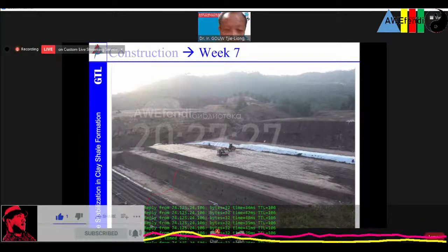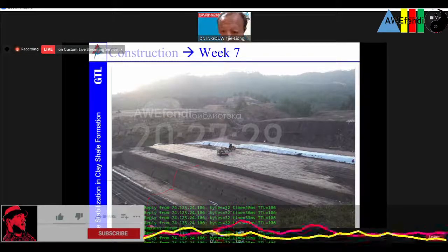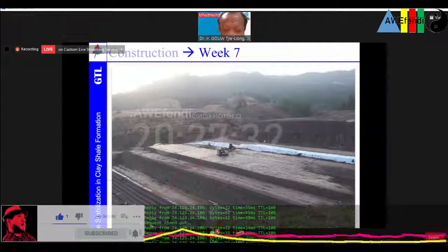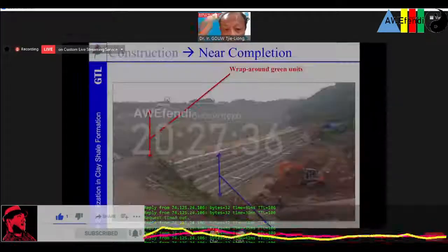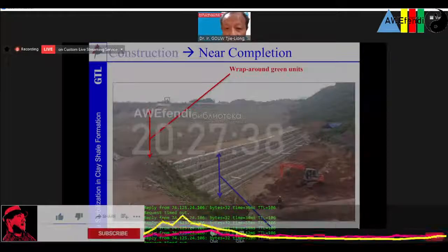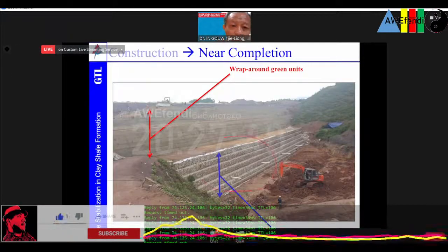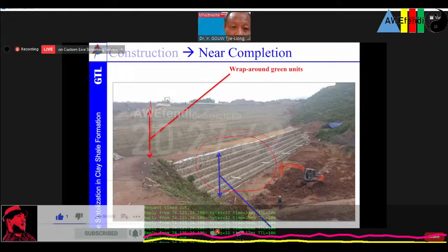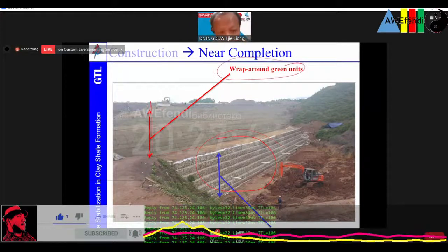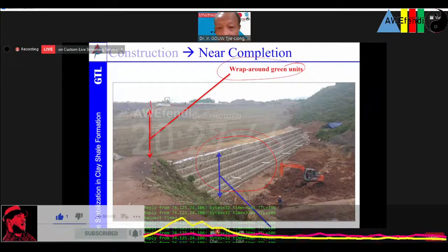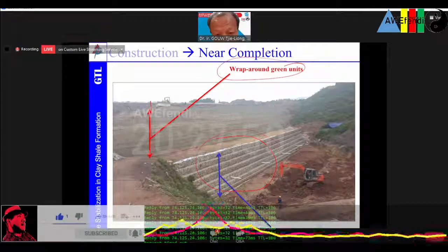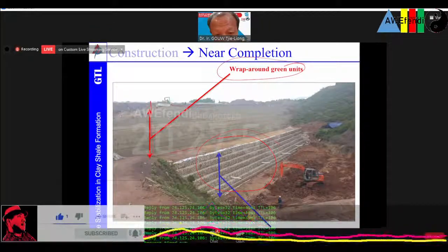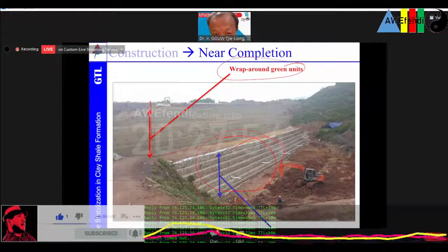Then we go up like that, up to the highest one, which is 37 meter high. So these are the base anchor gabion units, and then we have this green terra mesh. This is about 50% of it. We start installing the green terra mesh, not gabion anymore, with only the bottom part being gabion. Right.